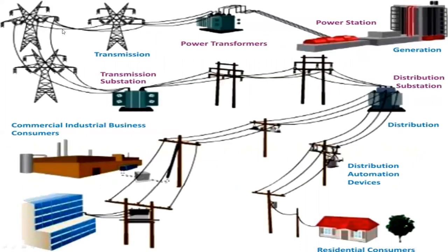We see we have the transmission to this, then we have the power transformers. So if you see the network from the power station, it is stepped up in the power transformer, sent along the lines through transmission lines, again transmission substations, then again distribution substations, where it is stepped down and distributed to different consumers: industrial consumers, residential consumers, and agricultural consumers. This is a very long ring main system of the electrical power system.